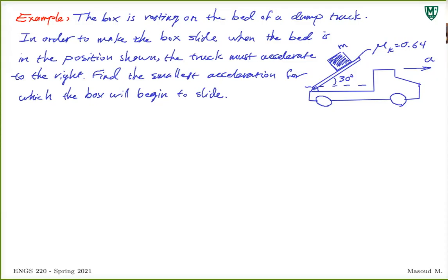Either of these. Isolate that, draw the free body diagram, draw the kinetic diagram, make it equal. Look at the equations, see if you have enough equations for your unknowns, and you can find what you're asked. So in this case, I'm going to isolate the box and draw its free body diagram and kinetic diagram.